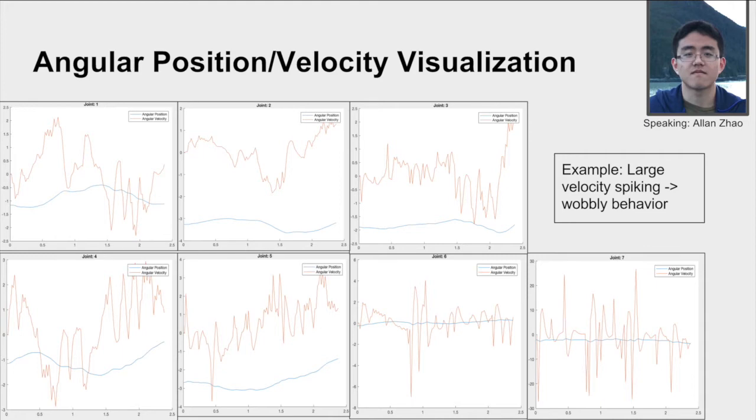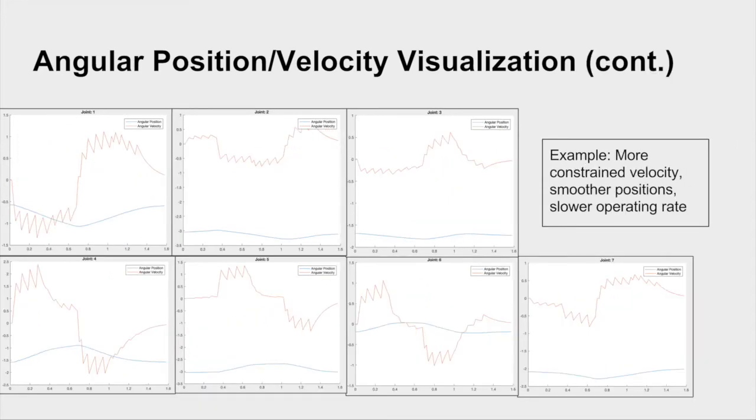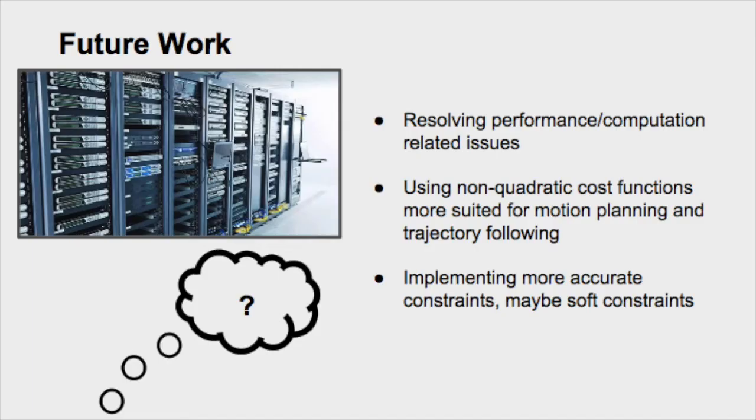We instead turned to plots of the joint states and velocities, and were able to clearly discern how high our joint velocities were rising, or how smooth the joint states were changing. However, while these plots were useful, without the animations of the arm's motion, it was very difficult to completely characterize the performance of our controller's settings. Both tools were invaluable to the interpretation of the data from the other.